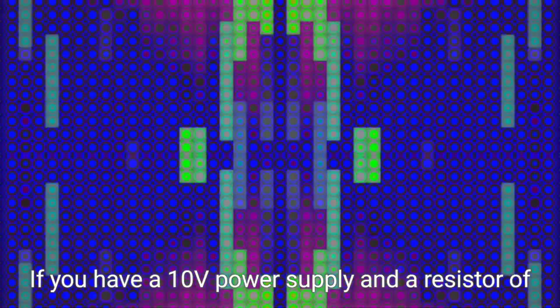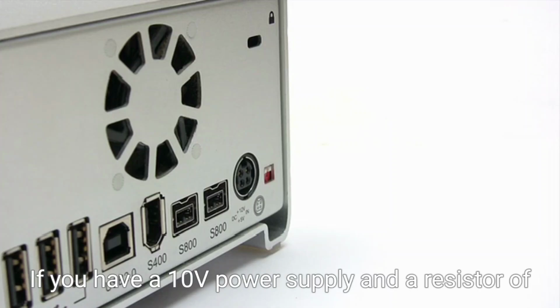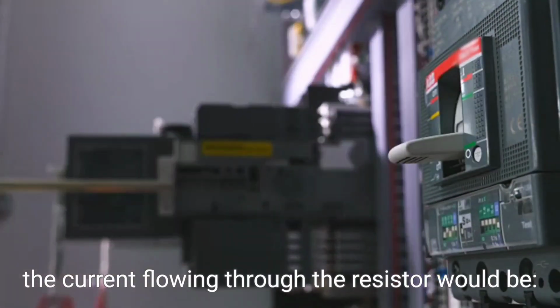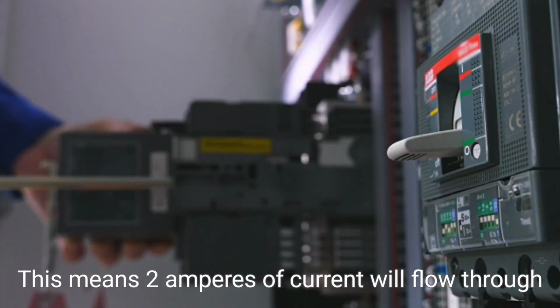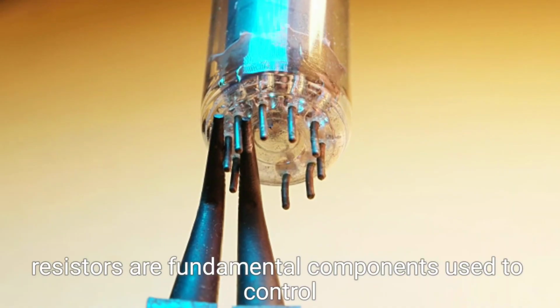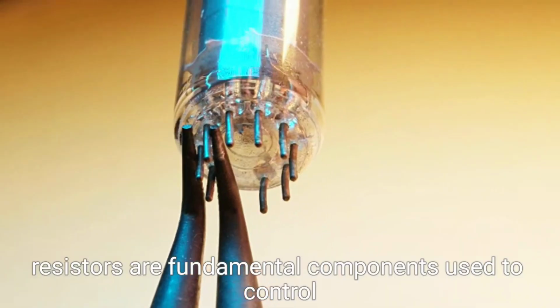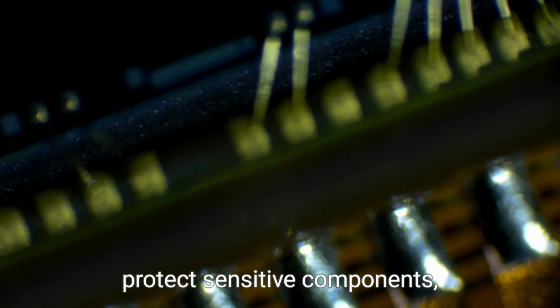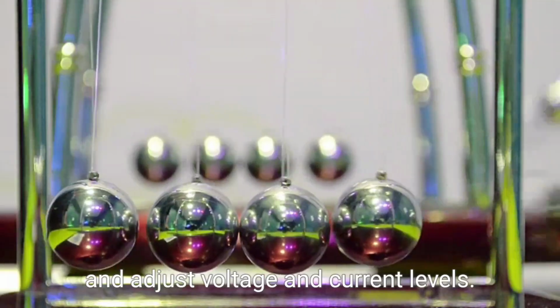Example: if you have a 10V power supply and a resistor of 5 Ω in series with a circuit, the current flowing through the resistor would be I = V/R = 10V / 5Ω = 2 A. This means 2 amperes of current will flow through the resistor. In summary, resistors are fundamental components used to control the flow of electric current in a circuit, protect sensitive components, and adjust voltage and current levels.